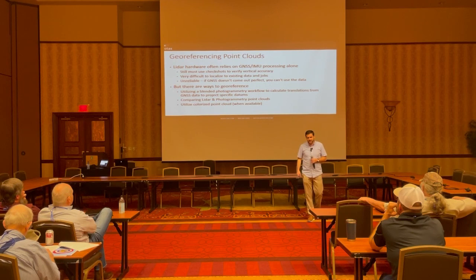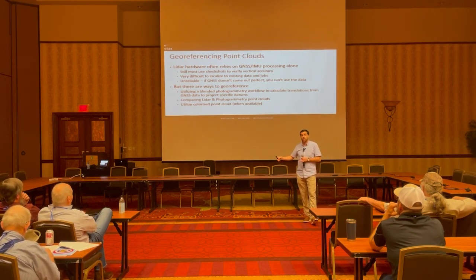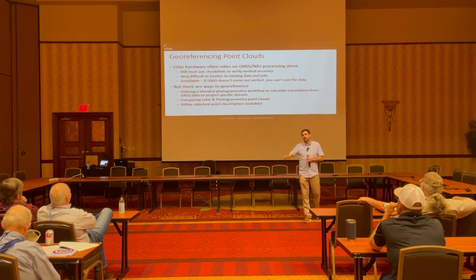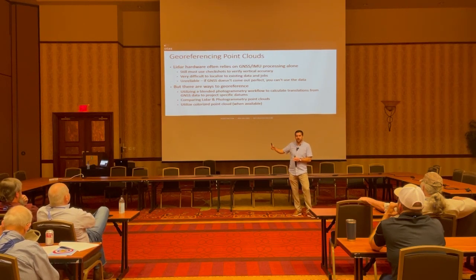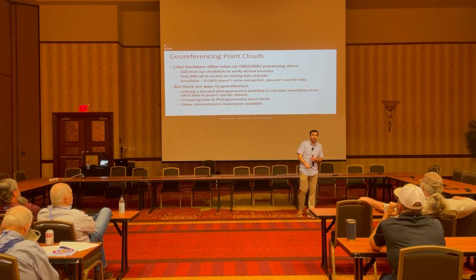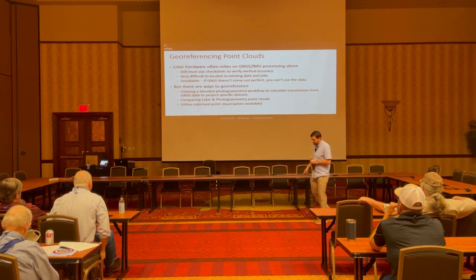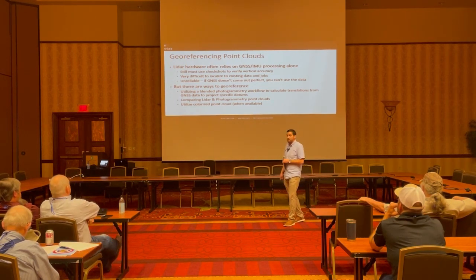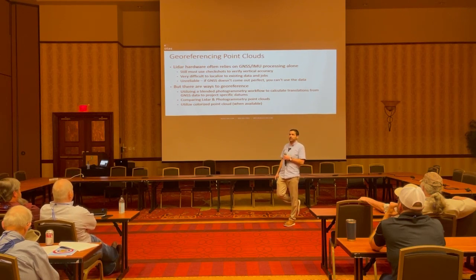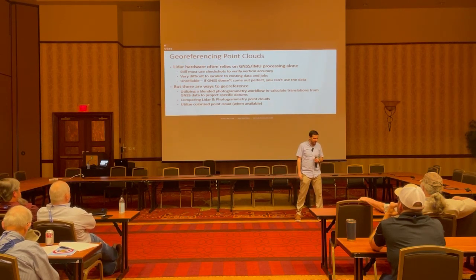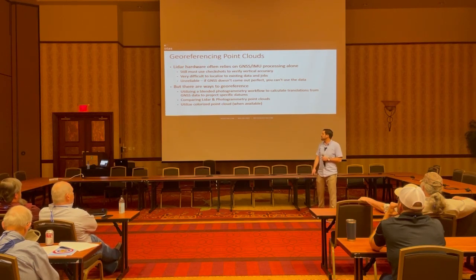There absolutely are ways to georeference and validate data, both with check shots as well as with using them as control points. You can control LiDAR data to an arbitrary 5,000 by 5,000 datum, or localize it to a project. You absolutely can very easily, and we recommend it. So I don't buy the arguments that LiDAR must be GPS processed only and can't use control. I found it again to be a much more reliable workflow for survey.